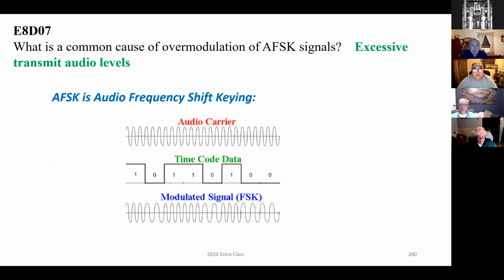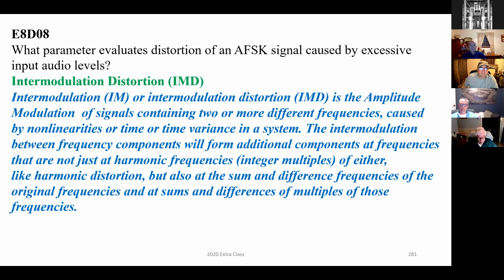What is a common cause of overmodulation of AFSK signals? Excessive transmit audio levels. What parameter evaluates distortion of an AFSK signal caused by excessive input audio levels?